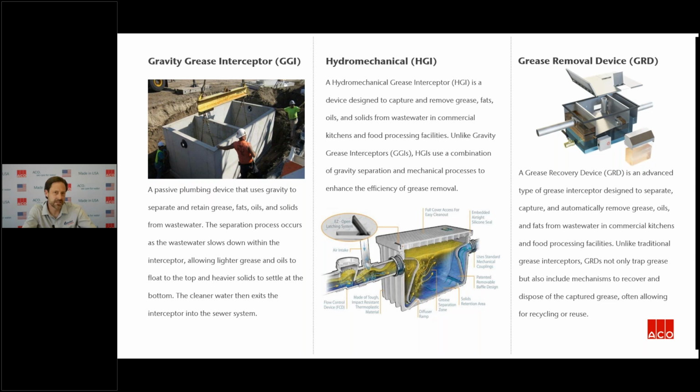In a sense, this is still a containment which still has to be pumped and the grease physically removed from the interceptor. And then we have a grease removal device, or a GRD. This is where you have technology that, through an automatic process, is siphoning or removing the grease from the water. There are a number of different technologies, and I'll dig in a little bit around all three of these.